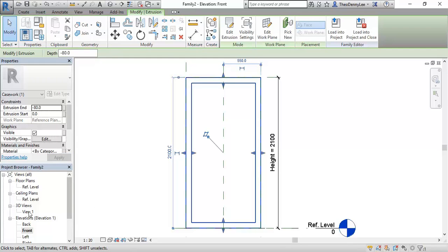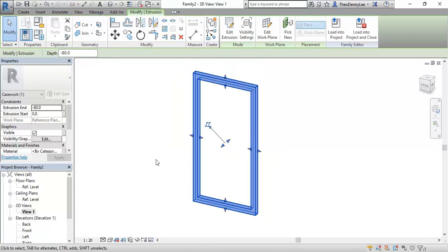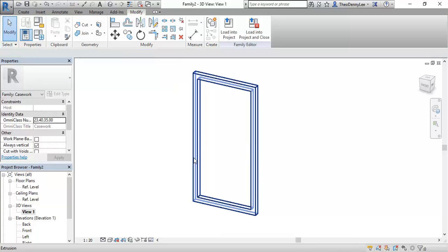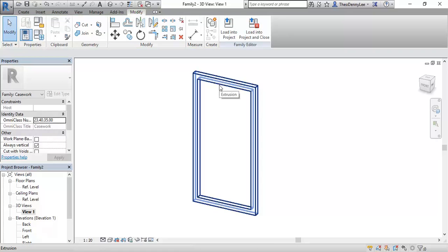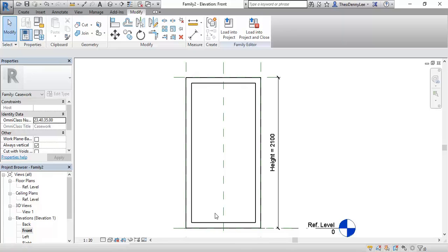Okay, and so because I modelled the extrusion in the front plane, I can put the hole in as part of the sketch for that extrusion, and that saves me from making a void. So there's lots of ways of doing things, and often you don't need to make a void, but sometimes it can be easier to make the solid in one direction and then the void can be in a different direction. So now to do something interesting